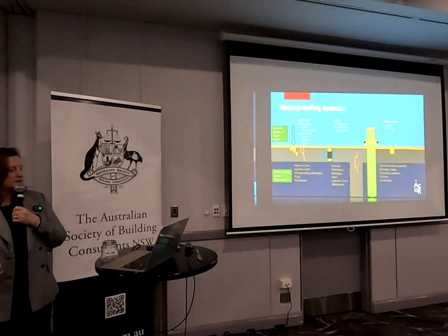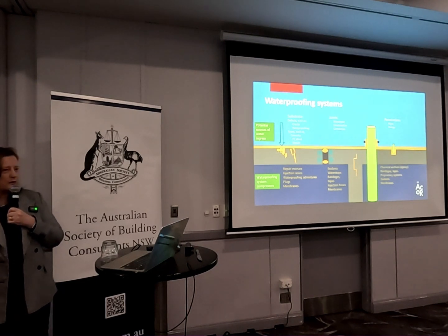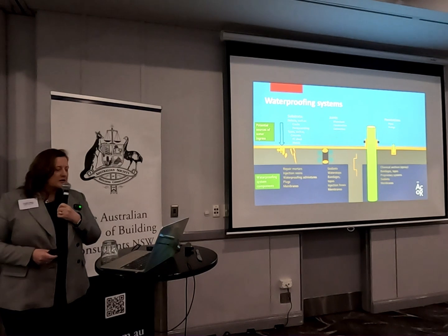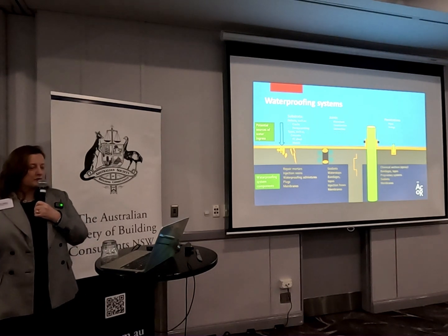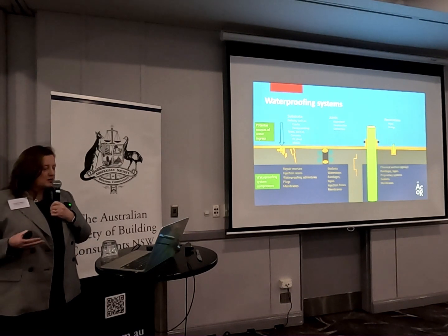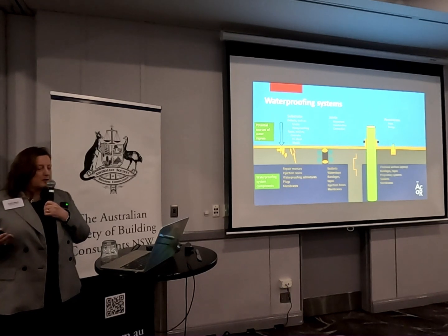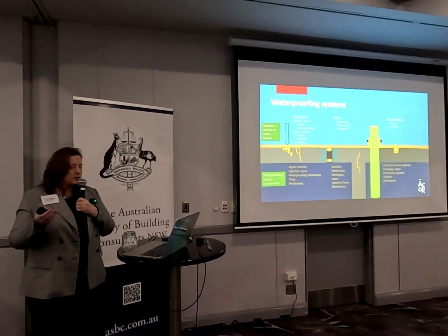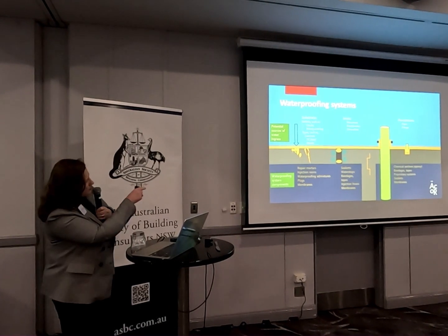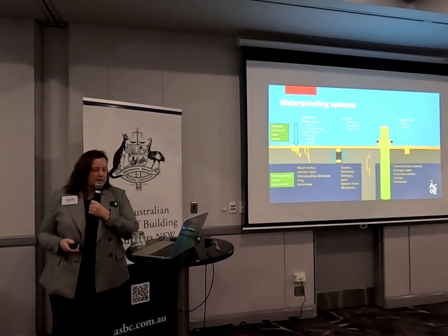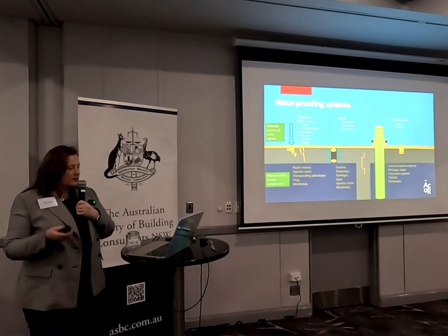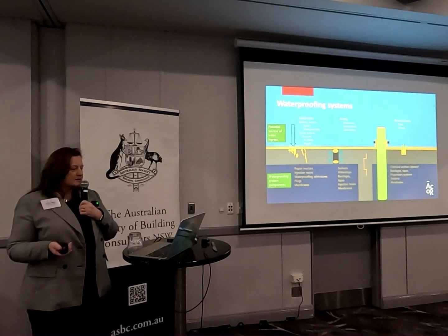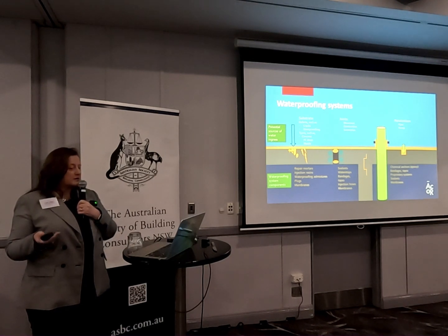And there's also a chance for me to experiment with drawing things on PowerPoint. So the yellow is meant to be all of the waterproofing treatments. With substrate, we can do repair mortars, we can do injections, we can do admixtures as well. You see the little dots on the bottom, that's meant to be an admixture there. The membranes, of course, can address the substrate water ingress. We've got the joints, sealants, water stops, etc.